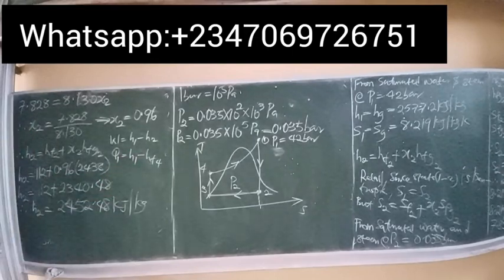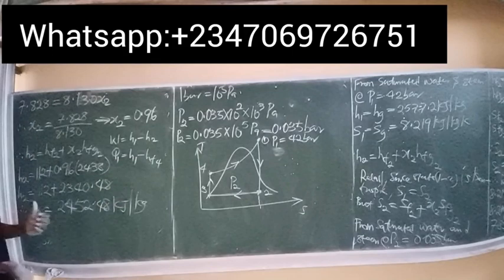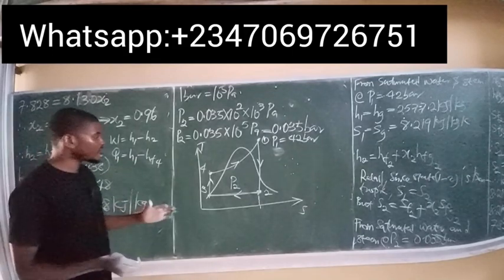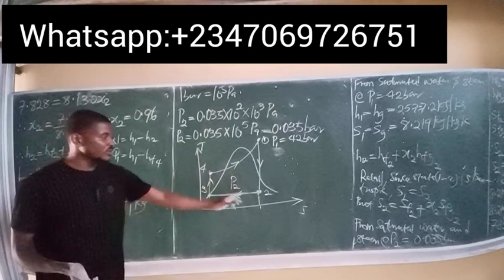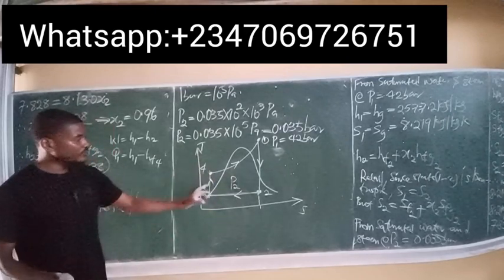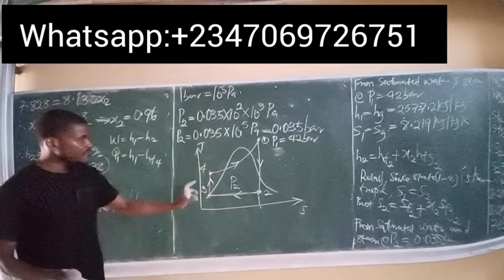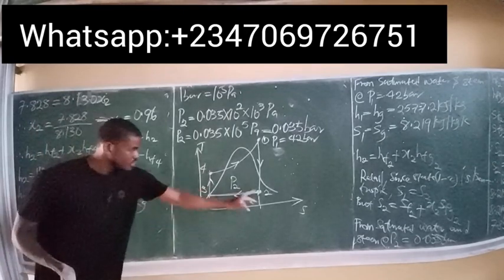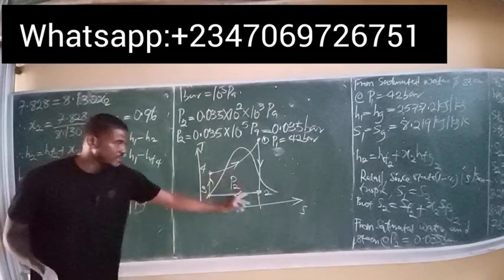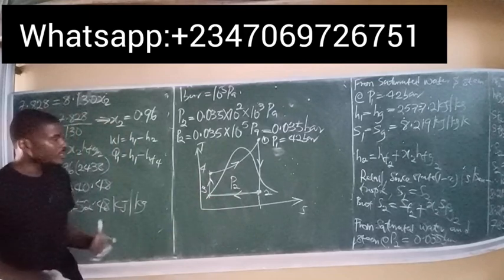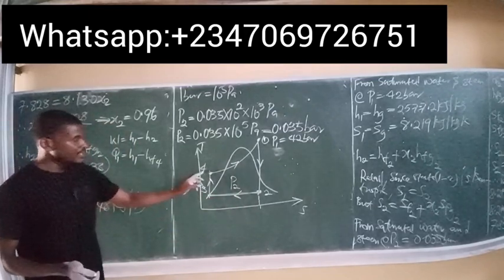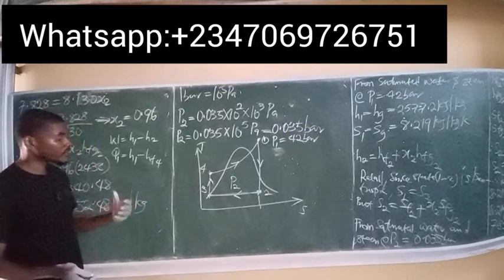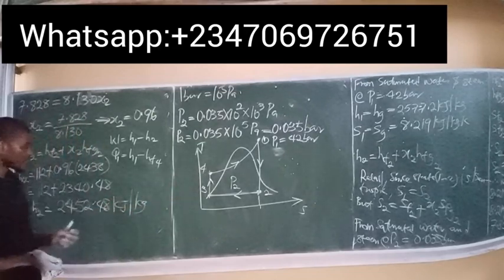So the way to find HF4 is simple. HF4 is simply the enthalpy at the given pressure. Since at state 4, everything here is completely fluid, the pressure governing this state from state 2, state 3 down to state 4 is simply the condenser pressure, which is 0.035. So we simply go at 0.035 bar, obtain HF. That value of HF simply stands for HF4 at 0.035 bar.